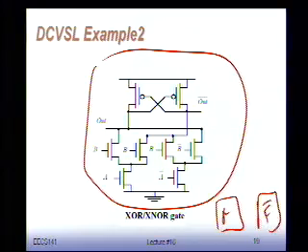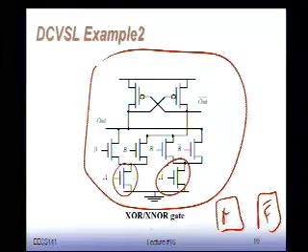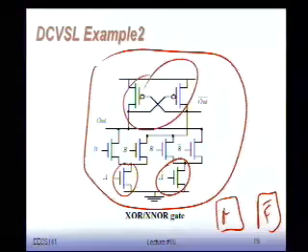You say, well, maybe occasionally I can share some transistors between the two. This one actually shares; those A and A bar transistors are shared between the two networks. And then the B's connect to the different outputs. So I can get away in XOR here with 6 transistors in the pull-down network and 2 in the pull-up network. And again, those can be fairly minimal size. They don't really have to be very big. So, an interesting logic family. And as I said, basically the same concept as ratioed logic, but it doesn't have the ratios anymore, and it doesn't have the static power dissipation anymore.